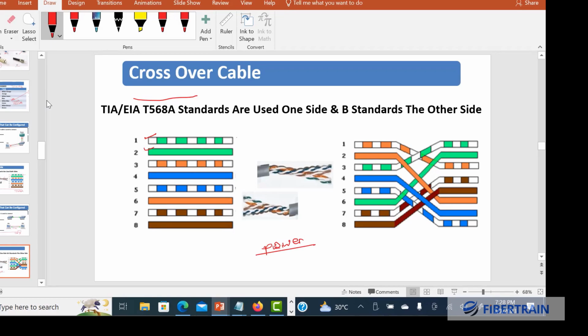And here white green green. This is white orange orange. Okay, so this is white, orange, blue; here is white, green, blue. Are you seeing it? Yes. And now here we have white, blue, orange. Here we have white, blue, green. And so the last two are always the same: white, brown, brown, white, brown, brown.